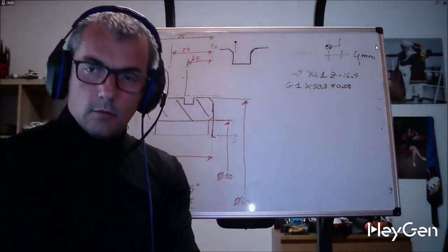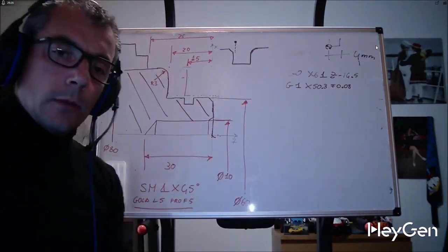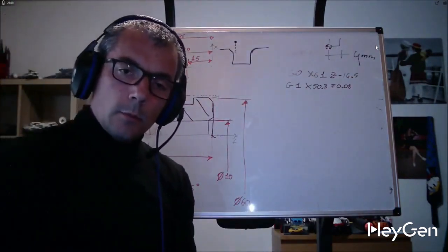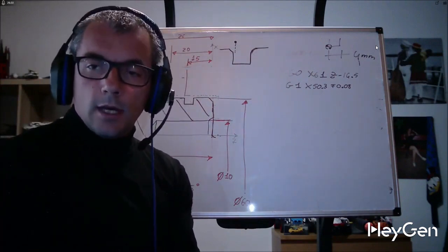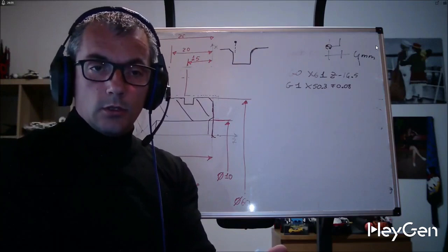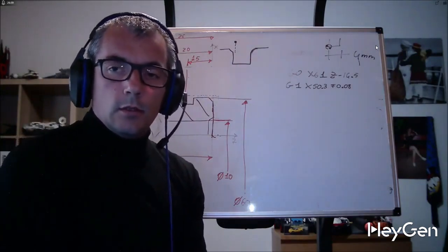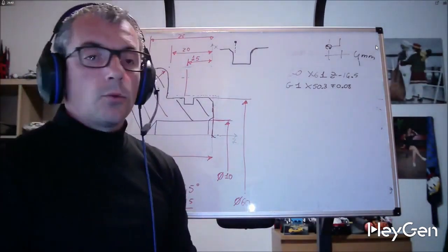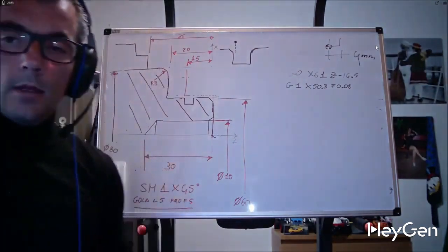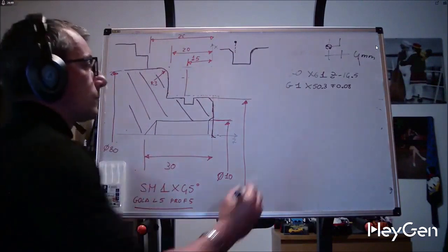We saw it for the tip. We go to X57. We back off by a tenth. X58. We back off by a tenth. And so on until we reach 50.3. This is to facilitate chip breakage, which is notoriously a pain in grooves.